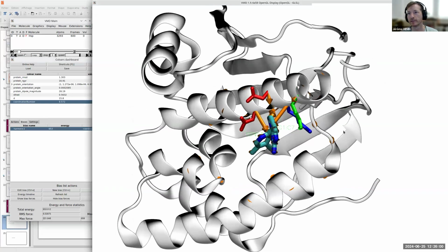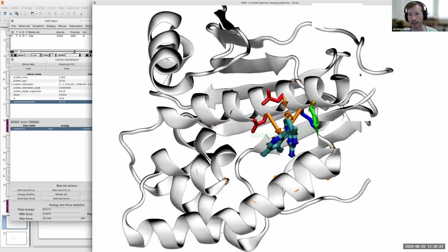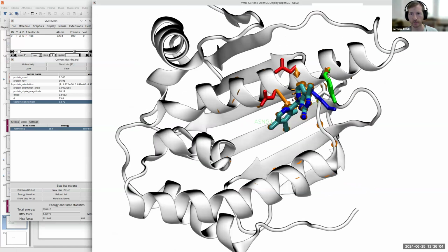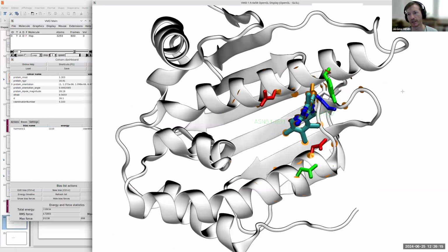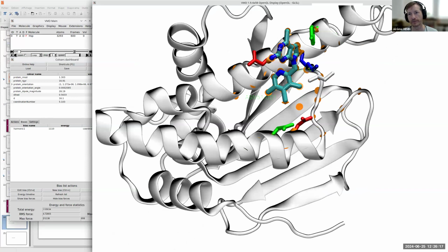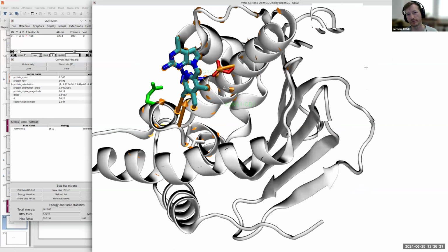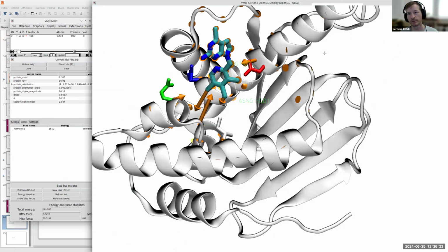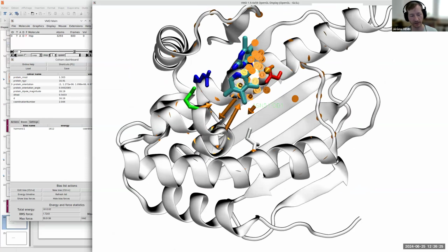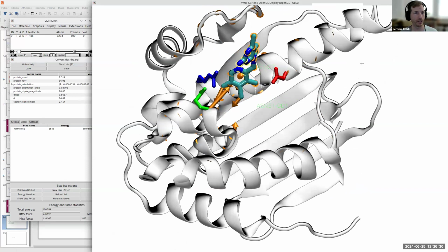Using VMD, I can do something like move the molecule even with my mouse. So here I say, what happens if the ligand is here and rotated instead of being there? Then I need to press F5 to refresh or click refresh, and it's just recomputing everything. So I can even look at what happens to coordinates that were not in the simulation, but coordinates that I've been modifying. Oops, here I'm touching the protein. So everything is updated every time I press F5 or refresh here.